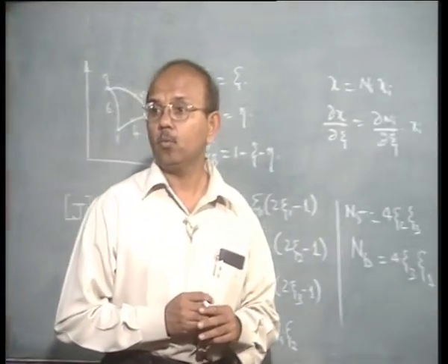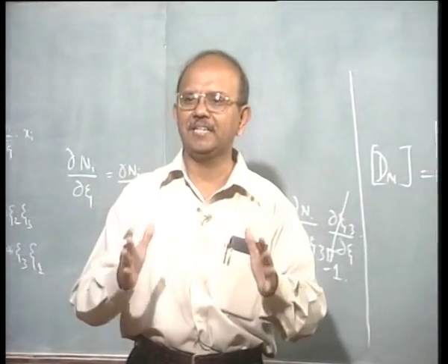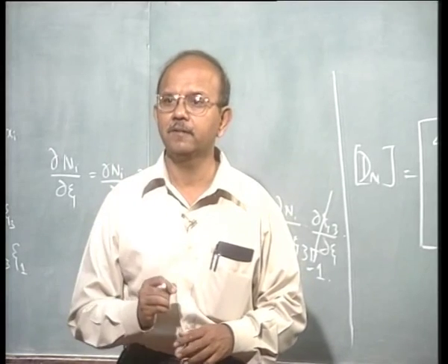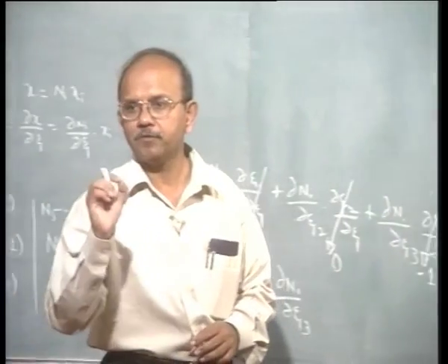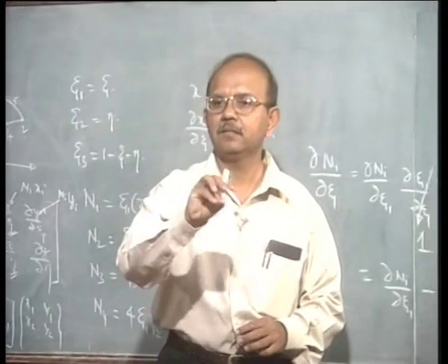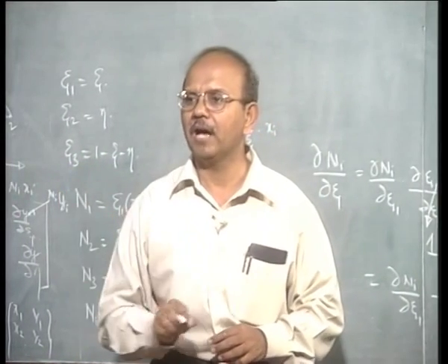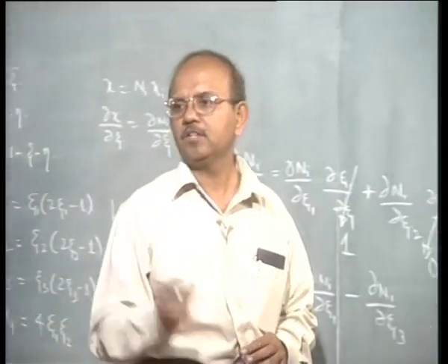When you do that area integral, the procedure is exactly similar to what we did before. We have some sampling points, we have some weights. So at these points we have some weights. So calculate this P transpose dBj at those sampling points, multiply by weights.